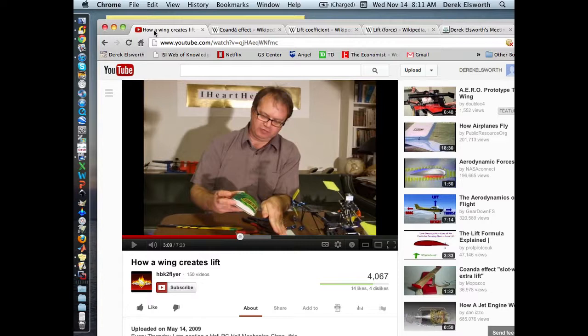And so the interesting thing about external flows is that typically, instead of being confined in the pipe, the expressions that we deal with are exactly the same as when we've dealt with pipe flow. But we're interested less in the drag in terms of what that affects the flow rate, and more in terms of what the forces are on the structure and how we use that. So the forces on the structure might be drag or lift. Drag, for instance, on a car, because the drag force that you apply on a car by the air flowing past it is the force you have to apply to push it along the road. And so if you multiply the drag force by its velocity, you get the power that you have to consume to get over that force.